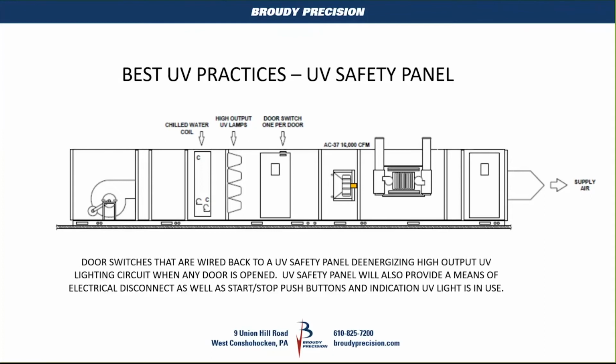And one of the variables on the intensity of this technology is that over time, the UV bulbs begin to dim or get less intense. So we recommend that they are replaced yearly, if not before a year, whether they're burned out or not. So it keeps them intense at all times.